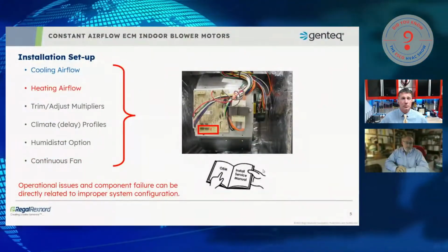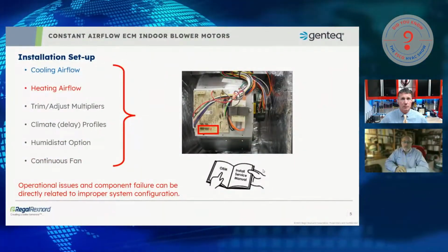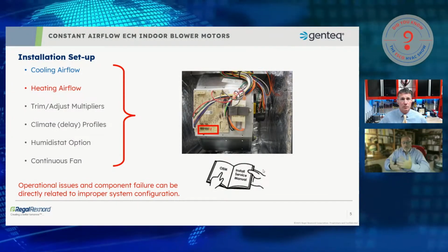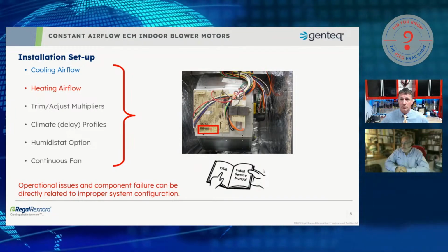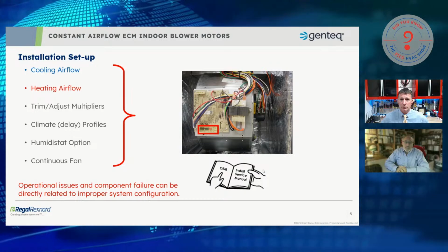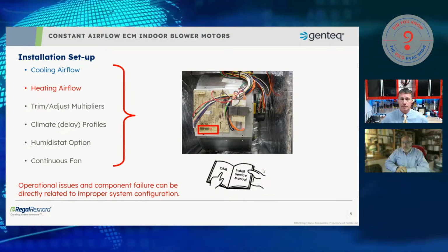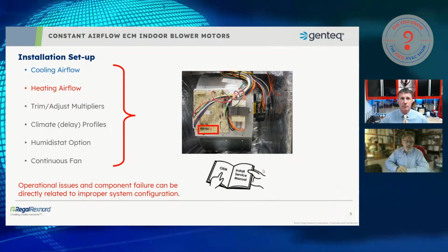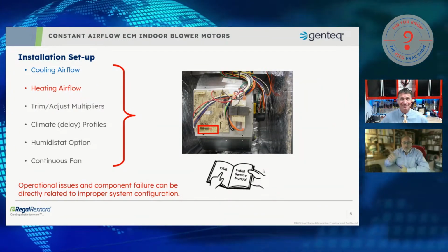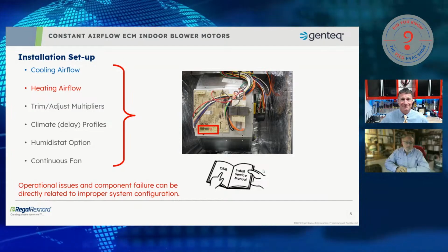Some of them are simple selections where you say, hey, I want more dehumidification, or some of them are more sophisticated where you can pick a profile that matches your market. And some of them are even more sophisticated where the unit will look at the humidistat or humidity sensor in the thermostat on the wall, and it will gauge whether it needs to go into dehum mode by what's actually happening to the conditions in the home.